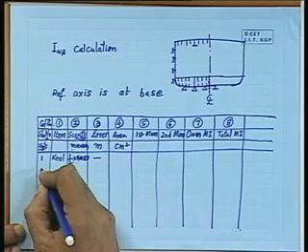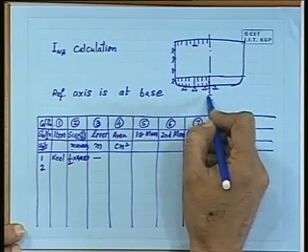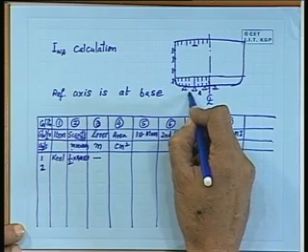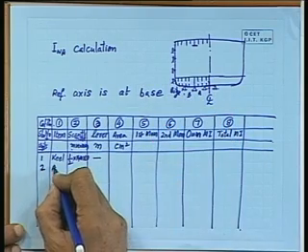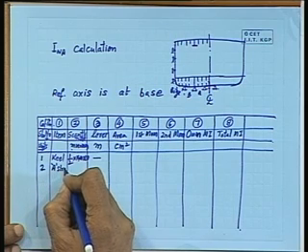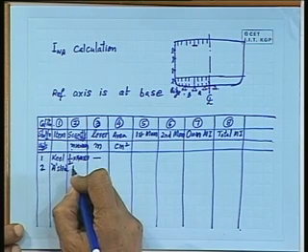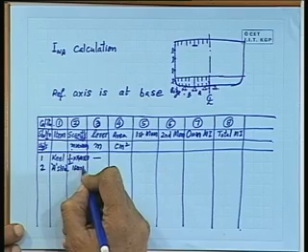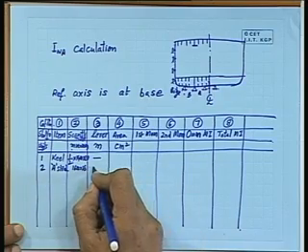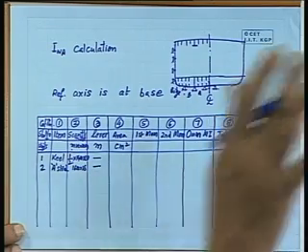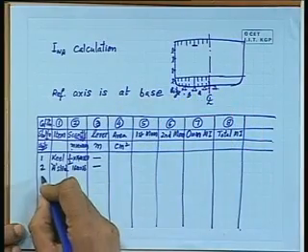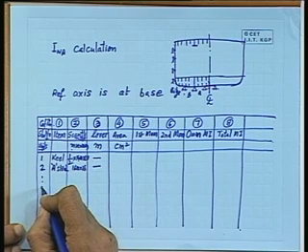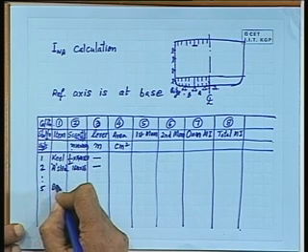Okay. Second item I take, say this is strake A, strake B, this may be the bilge and so on and so forth. I put A strake. I write say 1600 by 18 millimeter, and this lever is also 0 because I am considering it to be a flat bottom shape. So, like that everything will be flat here till you come to say item number 5, bilge strake.